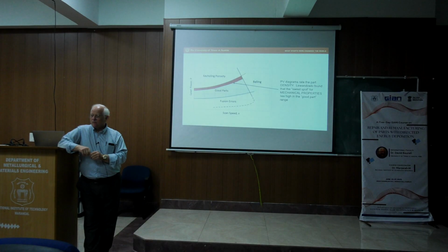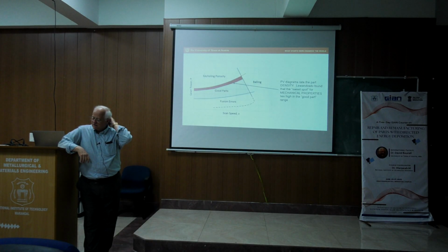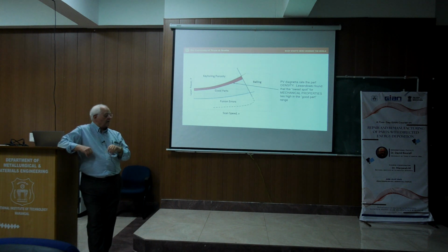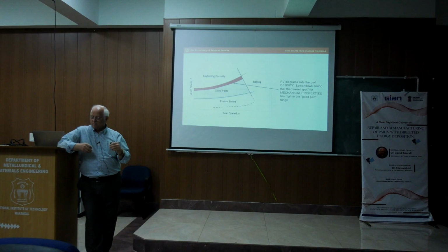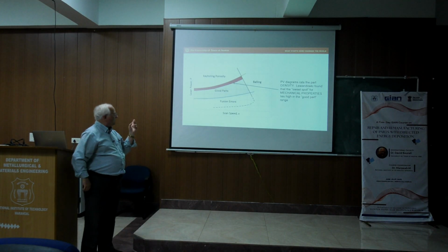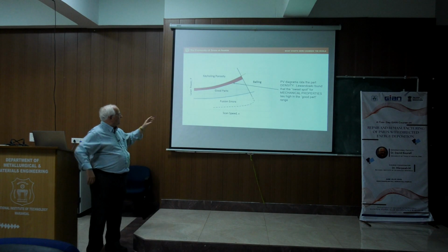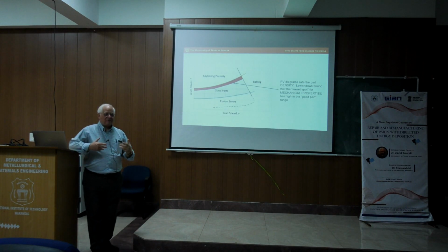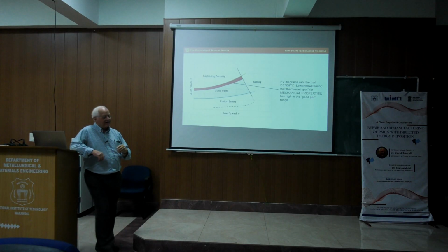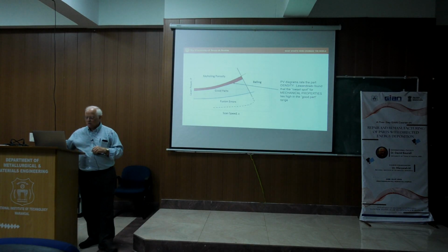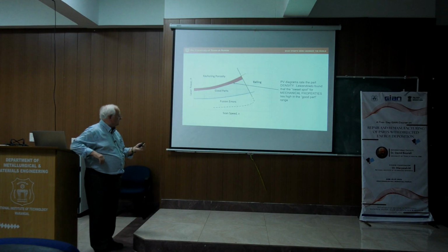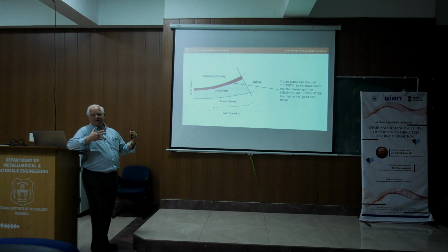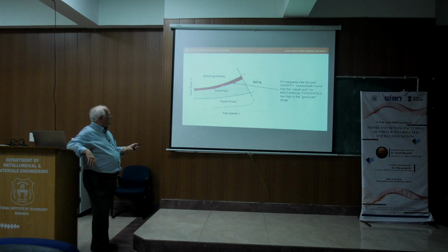Involved with that was a guy named John Lewandowski, who's a professor at Case Western Reserve, who was part of that team. He was looking at mechanical properties of these parts, and what he determined is that it's possible to build a good part and still not have good mechanical properties. And further, he noticed that where the good mechanical properties were was actually up here on the high power side of the good parts section.